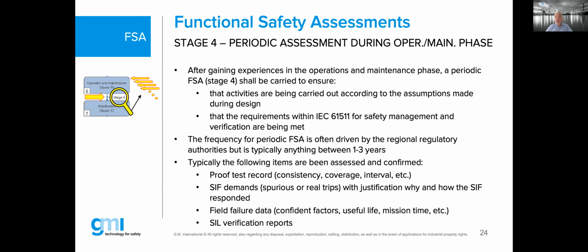Well, typically a useful life of such a final element has a reason. We don't achieve a safety culture by only start to replace an equipment that is failing or broken. That will not be the safety culture that the IEC 61511 wants to see, not even from the first edition. But we all know reality is of course different. People come with some data from a generic database, they will start to make calculation / estimation, and they all start to believe the numbers on paper, what they present to the inspectors. That cannot be the purpose of a safety culture of the 61511.